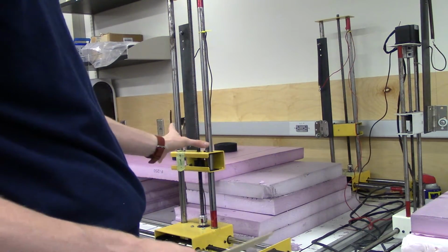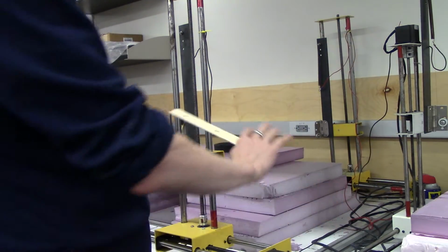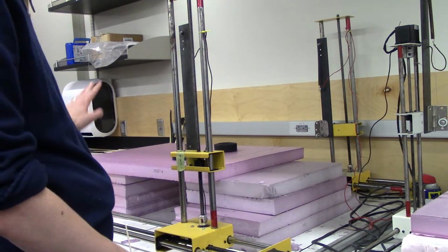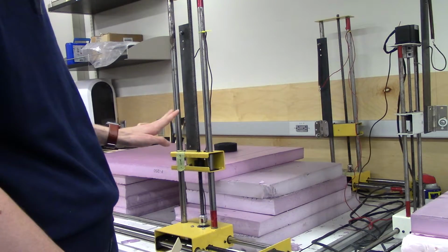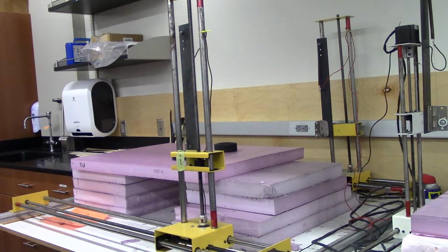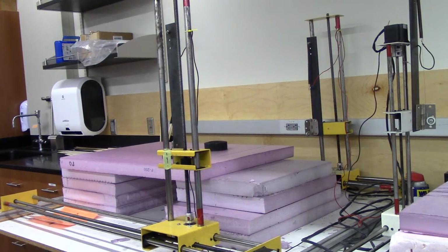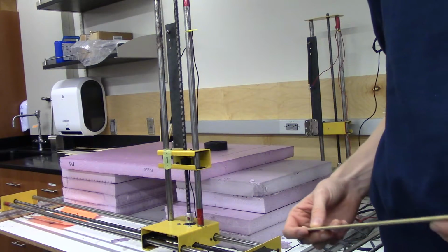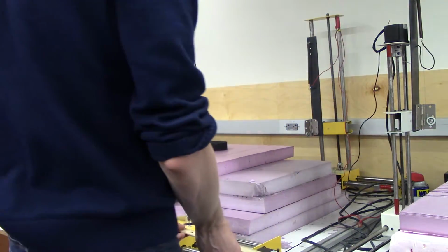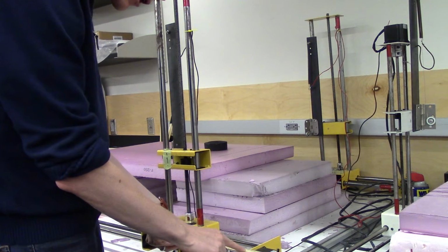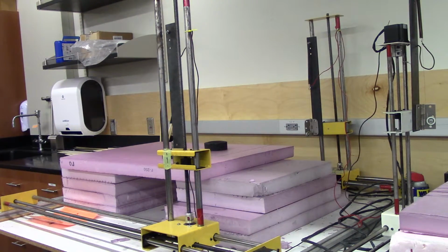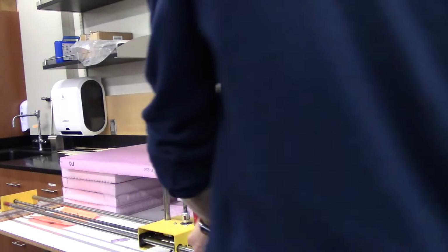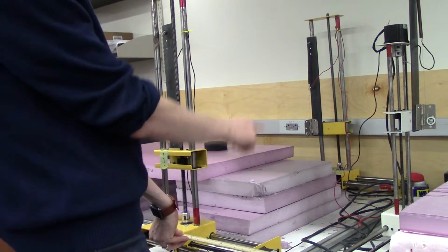To control this left one, your hands on the keyboard should do the same thing as looking at the foam cutters. So this left carriage will go with my left hand, the right carriage will go with my right hand. On the WASD keys, I'm going to move in the X direction to move that over 24 millimeters. This is often helpful to do with another member of your team. If you have two of you to do this at the same time, that's oftentimes recommended. Otherwise, you do a lot of back and forth. I only moved it about 1.5 millimeters, so I need to continue moving it a little bit farther. So I make sure that's centered on 24 and 24.